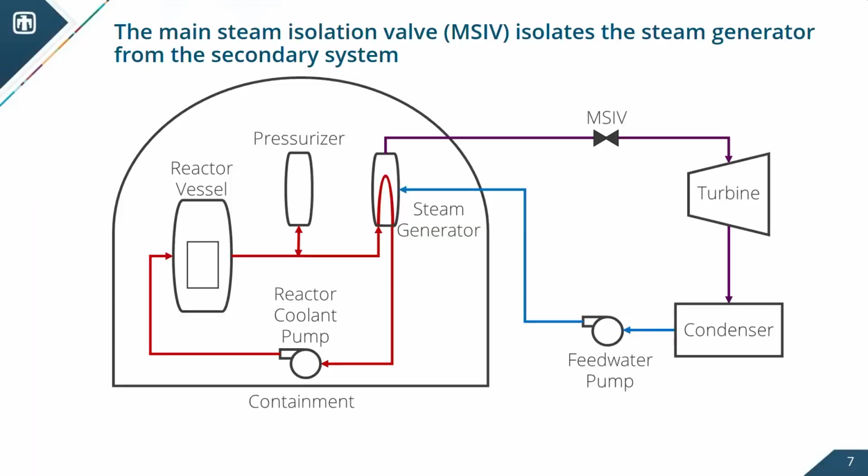One of the key safety events that could occur, and this is not from cyber, is something called a steam generator tube rupture, right? This is where you have a break in the steam generator tubes that results in the loss of primary coolant, which is light water, from the red primary loop.